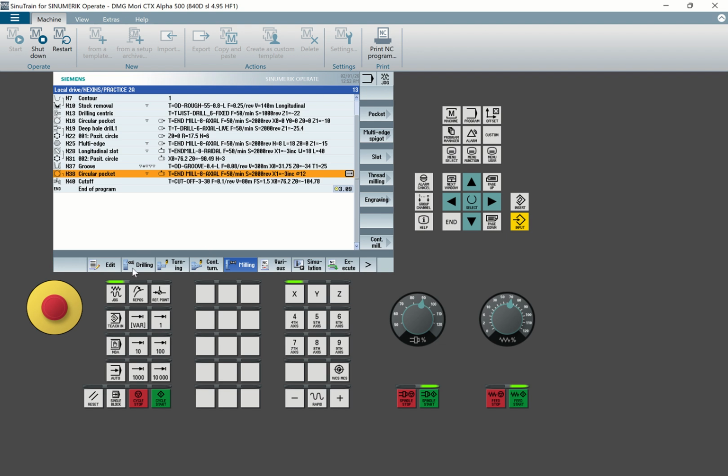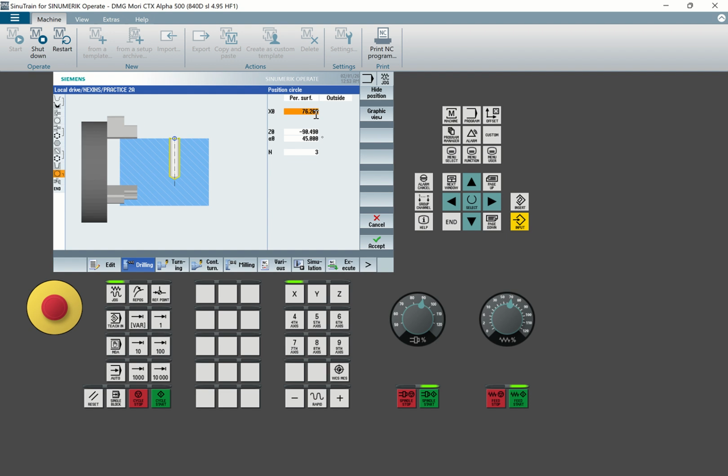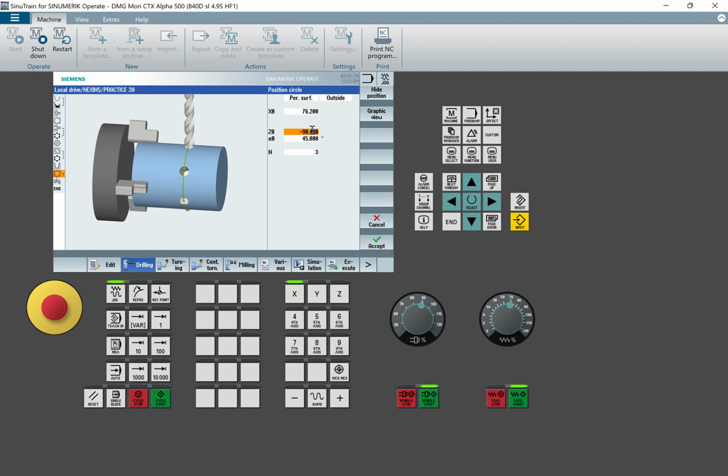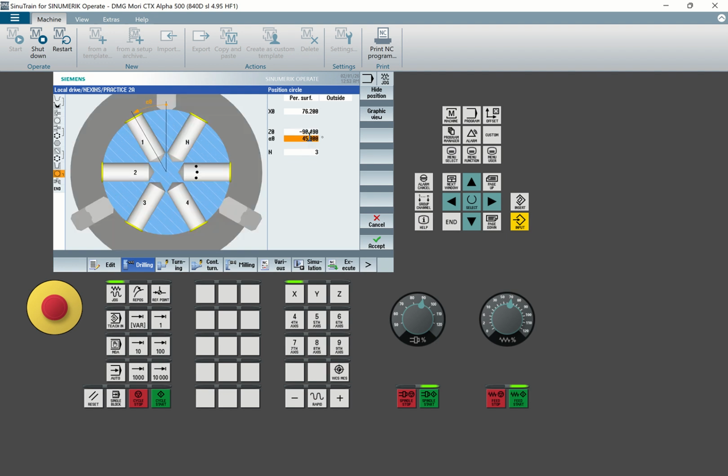Okay, and then I can come to drill, check the pattern. From this pattern, this is face C. The diameter is 76.2, for example. Z, I want to go to Z. Let me check the length that I put. I want to put 104.78 minus 76.2, divided by 2. You get this one plus 76.2 and get minus 90. So let me put 90, that is okay where it is. By this one, let me put 0.